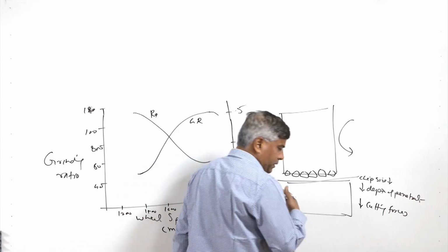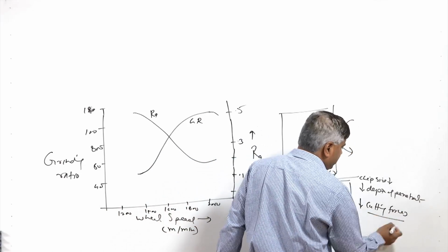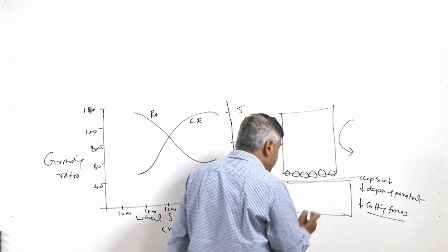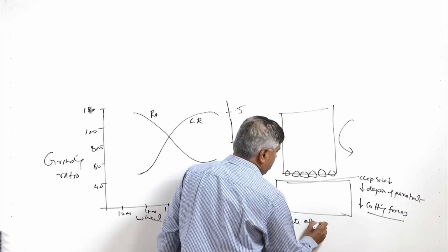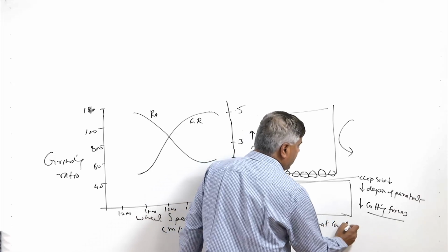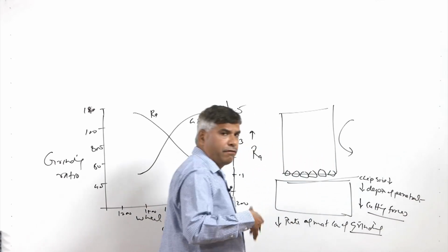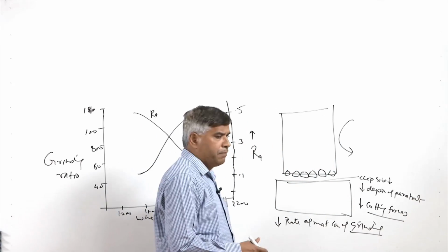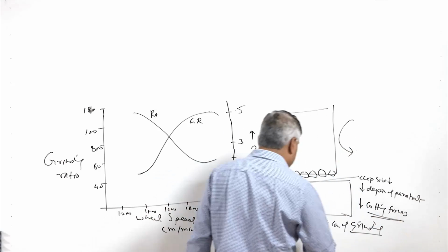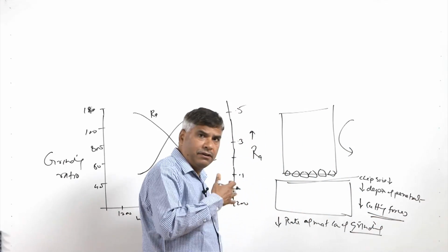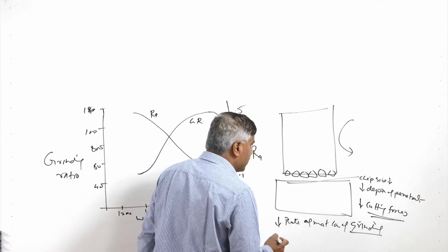Since the reduction in cutting forces leads to a reduced rate of material loss from the grinding wheel in terms of grain fracture, attrition or bond fracture, it reduces the severity of all those operational mechanisms responsible for the loss of material from the grinding wheel.